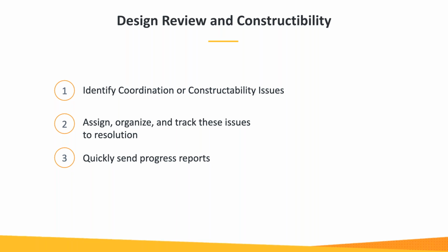I'd say if you're in early stages of design, this might be captured in one of your revision sets that you publish out later down the line, whereas if this is more in the later stage, it might be captured in a construction bulletin or an ASK. In either case, what you can do is either publish out that new revision or capture all the information into that ASK and then manually hyperlink it, like we were doing with the submittals, to that location on the plan.